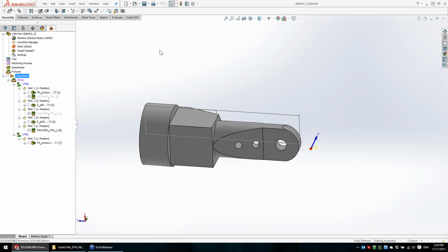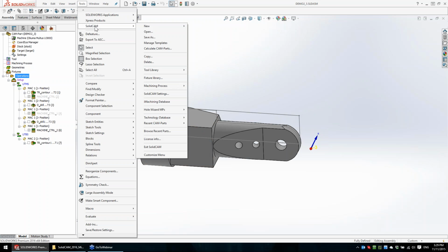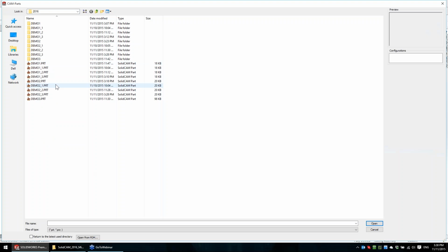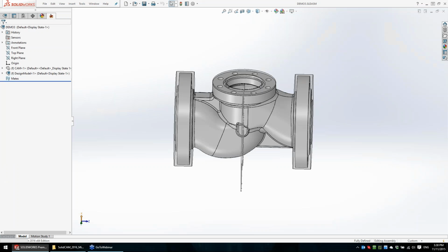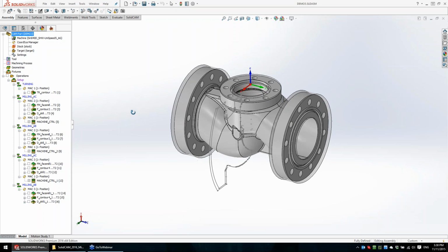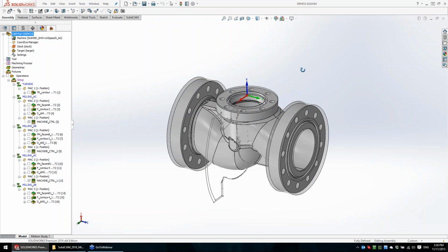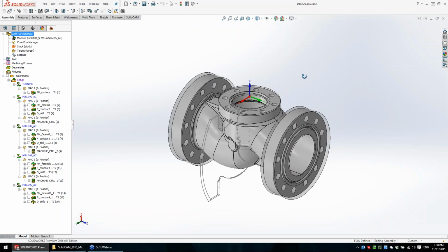Let's see the third example, and here I will use the same previous machine, the vertical milling mill turn machine, to see how we work with multiple coordinate systems, Multi-MCS. This option is used by castings manufacturers who want to work on castings, and on the drawings you have a lot of datum points.